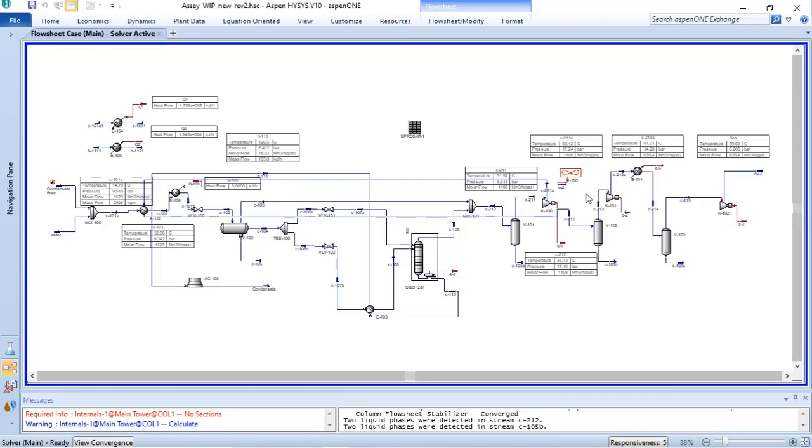If we cannot save the after cooler at the compressor discharge, at least the plant operational expenditure will be lower, because instead of using an electrical heater to heat the stream to the three-phase separator, we will be using the discharge temperature of the first stage compression. And with that, my friends, I finished the evaluation of the simulation.